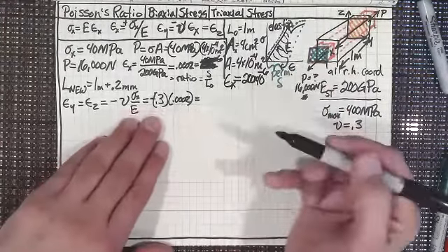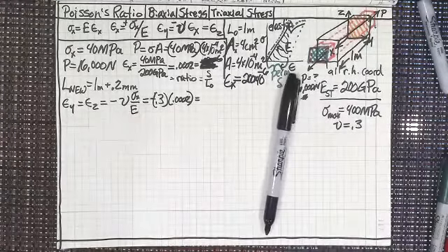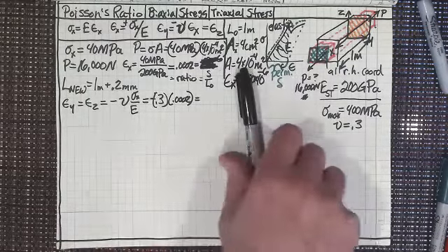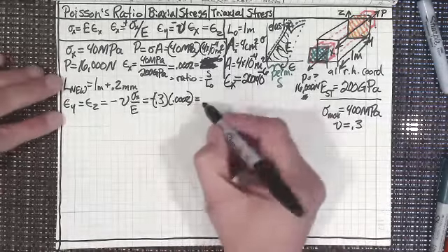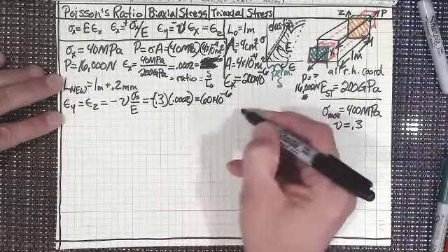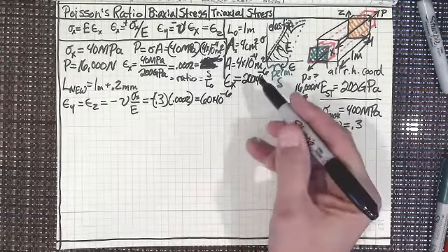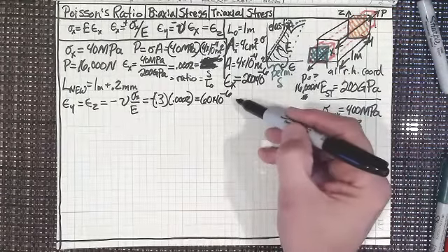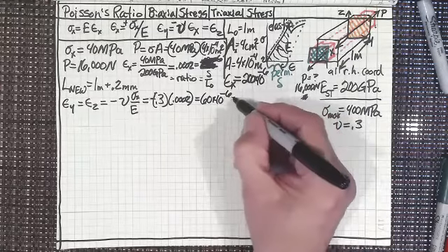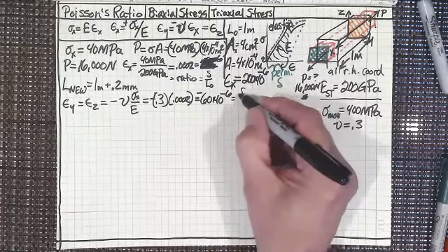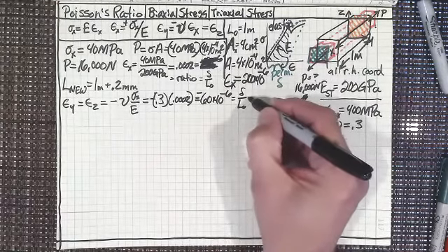And so if I'm multiplying this, 0.3 times 0.0002, that gives me 60 times 10 to the minus 6. And again, no units because it's strain. Strain has no units, stress is in pascals. So that's what I've got, but can I turn that now that I've got that strain? I know that the strain is the deformation over the original length.